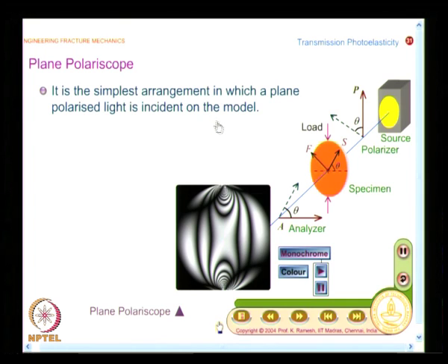When the ray hits the model, we label the axes as fast and slow axis, though we have no knowledge whether this is the fast or slow axis. This is only a representation, and it matters when I go to digital photoelasticity. For the optical arrangements in conventional photoelasticity, whether it is fast or slow does not make much of a difference.